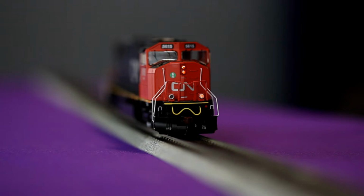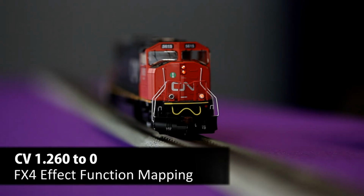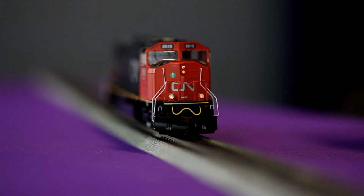Now the other ditch light should be set to function 25, but we're going to change that to 0 too. So we're going to take CV 1.260 and we're going to set that to a value of 0. Now you're going to notice the headlight and both ditch lights are on. When I turn function 0 off, they all go off together and they all turn on together. That's how function mapping works. So once you determine for yourself which buttons you want to control the lights, you'll set the CV to the respective value that corresponds with the button.